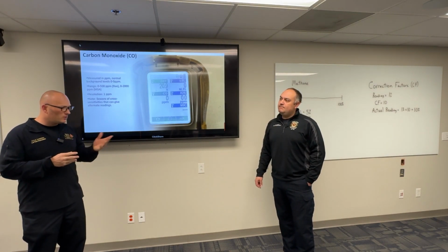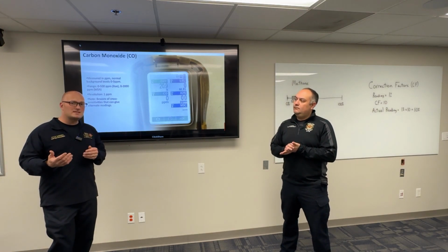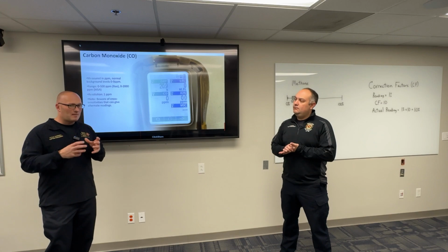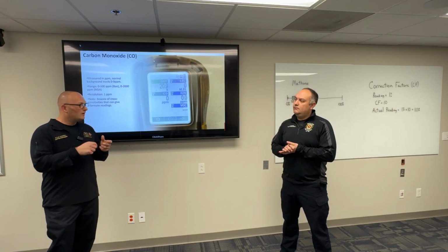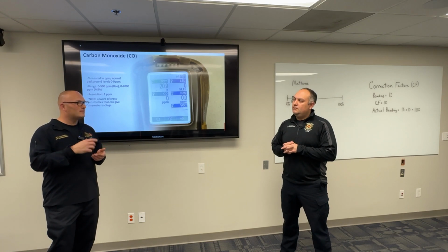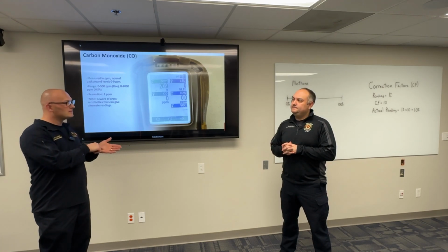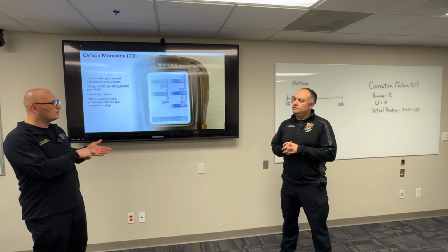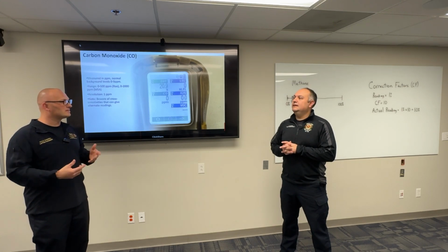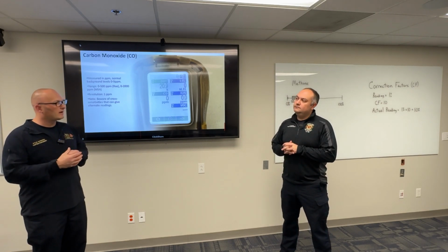So something else we do a lot, I think you guys at Creve Coeur probably do the same. When we're investigating these CO calls, I pull off the detector and look too, because we revoke the man cards, and you run those calls like, oh, this thing chirped 5 or 6 times, and actually explain to the people, hey, it chirped this many times, it means that you need a new detector, or it means that you've got this. It's not necessarily CO calls, but still go through and check everything.